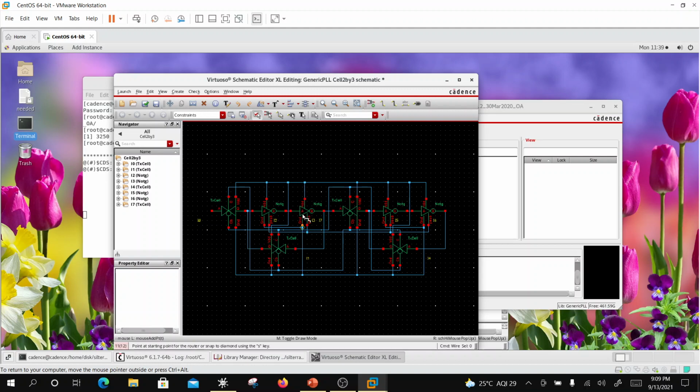So I can get rid of this NOT gate over here if I pick up from the output from here. And then I might not need even this cell because this can act as a floating node, okay? And a floating node, if the leakages are minimized, then I can even get rid of this transmission cell to make it faster. Okay, so I'll do that first.